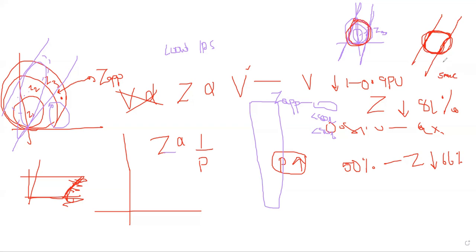I think, right? But there is one setting actually, that is for the disturbance, the relay will think this is the real fault or this is the power swing, because a power swing also comes like an impedance change only, and a fault is also an impedance change only. Both come below the line length actually. But the relay should identify this is the real fault, this is the power swing. Maybe within the time limit, if it is happening very fast, that's a real fault. If it is happening slowly, more than 5 milliseconds, maybe it will be a power swing, correct? But there is one setting, that is what I'm asking.